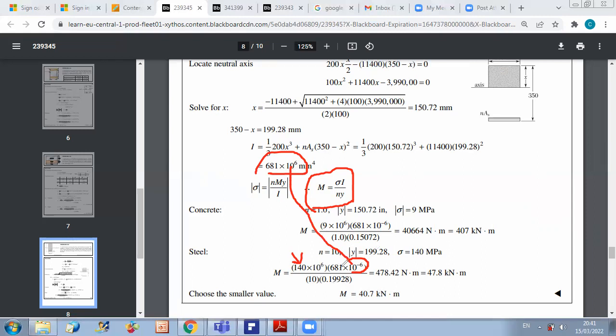Over, now keep in mind that for steel, because you have a modified section, the stress value is multiplied by n. This is why, when you get sigma maximum allowable, it's n M y over I. So to get the maximum bending moment, you divide by n times y. n is equal to 10 as calculated previously.